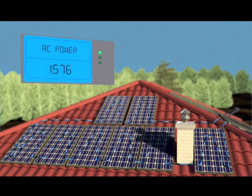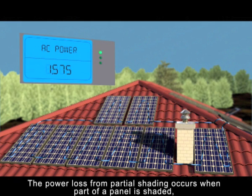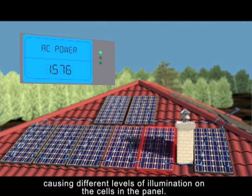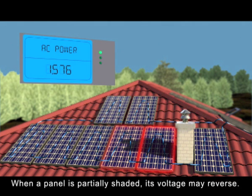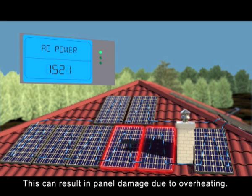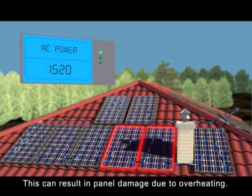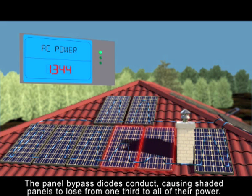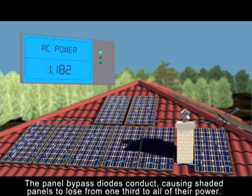The power loss from partial shading occurs when part of a panel is shaded, causing different levels of illumination on the cells in the panel. When a panel is partially shaded, its voltage may reverse. This can result in panel damage due to overheating. All PV systems prevent this in one of two ways. The panel bypass diodes conduct, causing shaded panels to lose from 1/3 to all their power.